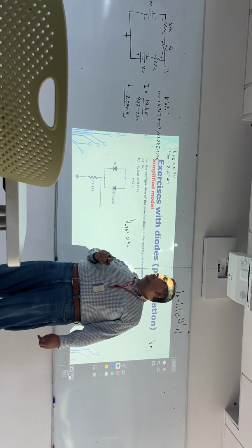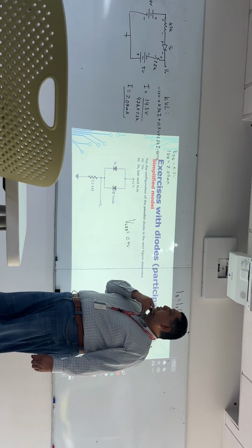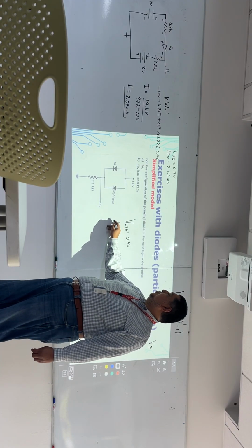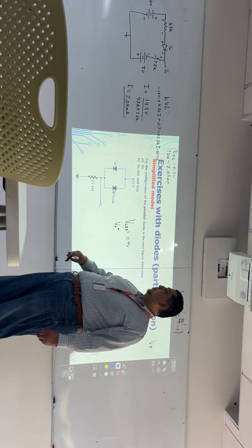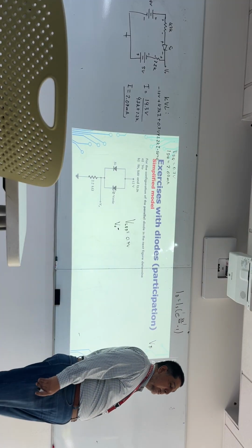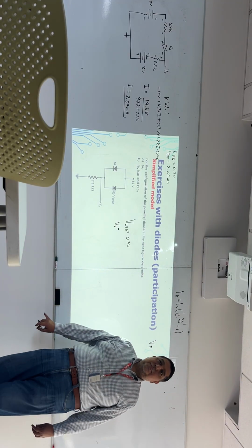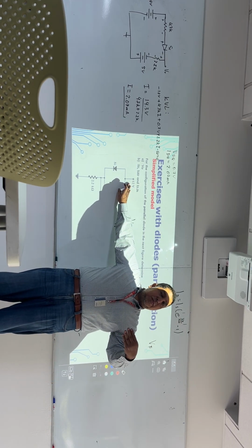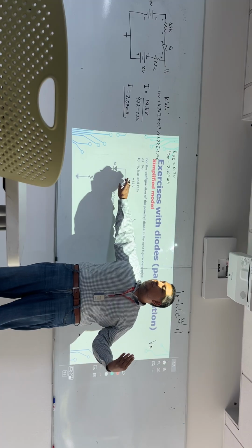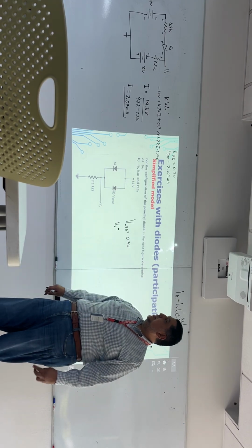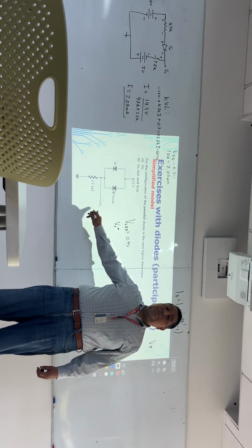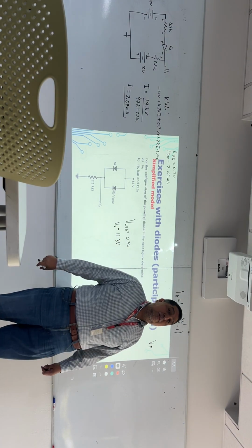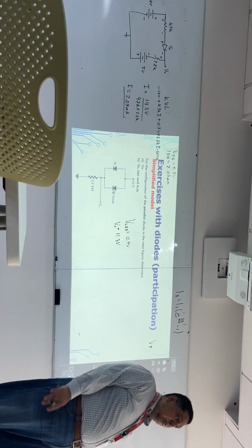This is very important. Now we know that, again, without writing any equation at all, you need to be able to tell me what is V0. How can we get V0 without writing any equation? That's going to be 12 minus, same methodology, 12 minus this voltage, this is 0.7, and then you have reached V0. So V0 is going to be 11.3, without writing any equation.